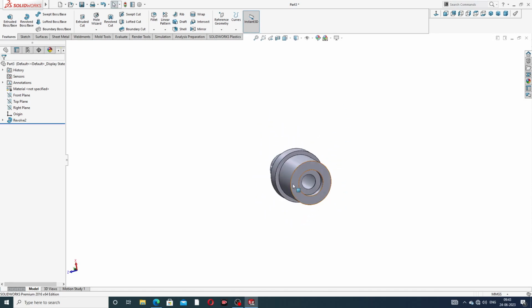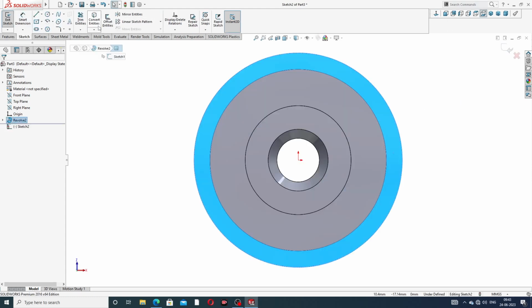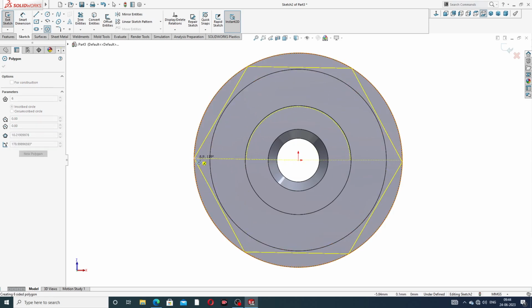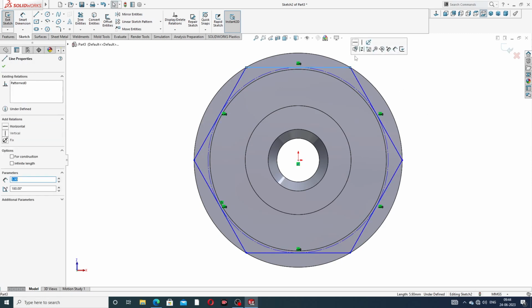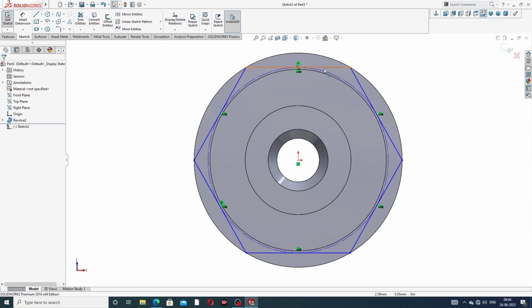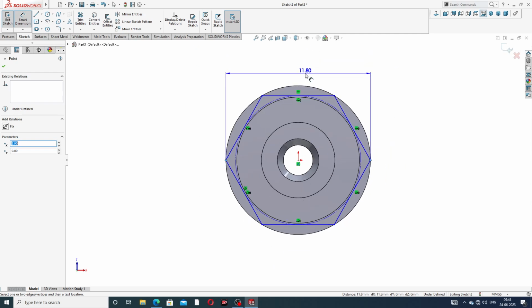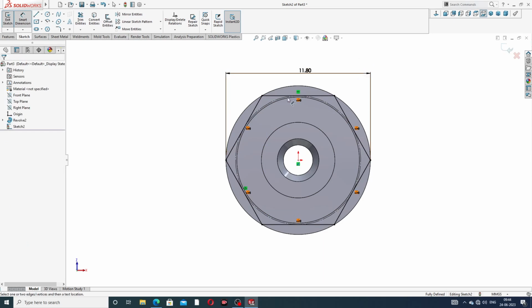and next this face, select sketch normal, and click a hexagon and select this, connect to this center point. Okay, and this line is a horizontal line, and mention this dimension, but this dimension is not used because this is connected here, and this dimension is perfect, 11.8.